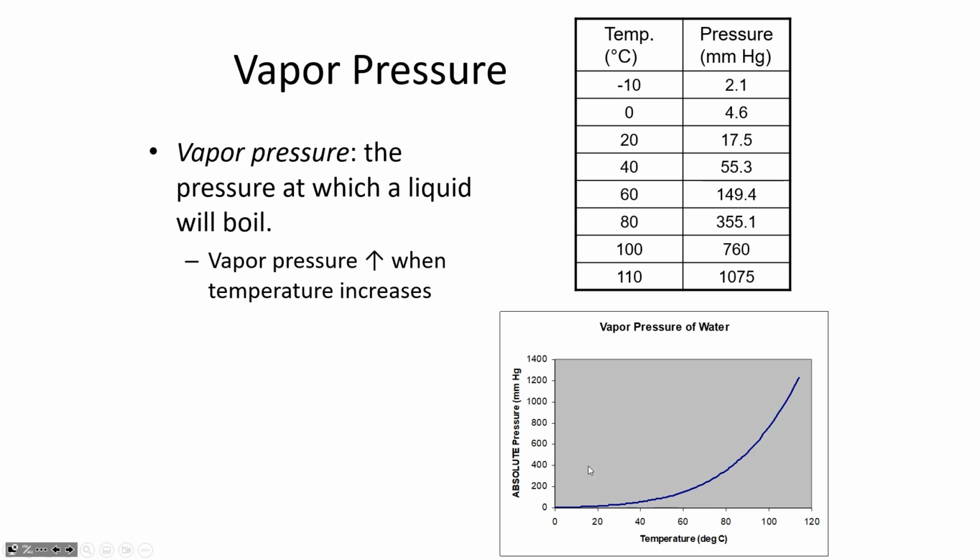Cavitation can form. And the critical threshold is if the pressure in this throat gets below the vapor pressure, then that's when cavitation forms. So for example, when you were in the lab, the water was probably about 20 degrees Celsius. So the pressure that it's talking about here is absolute pressure, not gauge pressure. In the lab, it's probably 100 kilopascals, or about 750 millimeters of mercury.